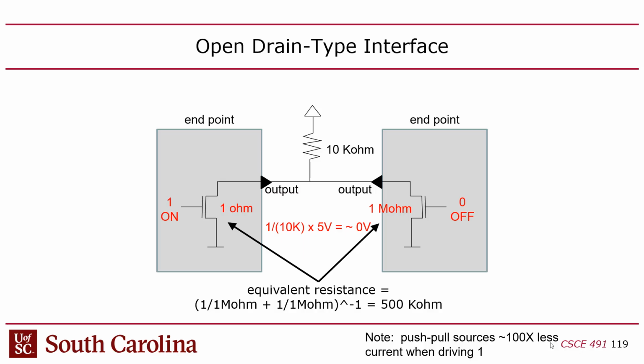Yes. Are these slaves or masters? Well, the idea is that we want to create a multi-master bus. So you have the potential to have different devices take mastership. And basically the way they take mastership is that they put a signal out on that wire, right? Now the presumption though is that this wire is an output, but it can also be read simultaneously as an input.